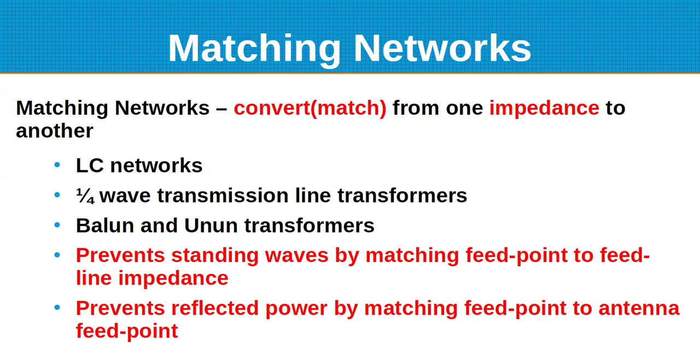And if you have a quote antenna tuner, which may be built into your radio or it may be external, if it's a manual one, you're going to have 3 knobs on it. And usually it's going to be what we call a pi network. So you'll have a capacitor across the input, a series inductor, and then another capacitor across the output. And all of those are variable.